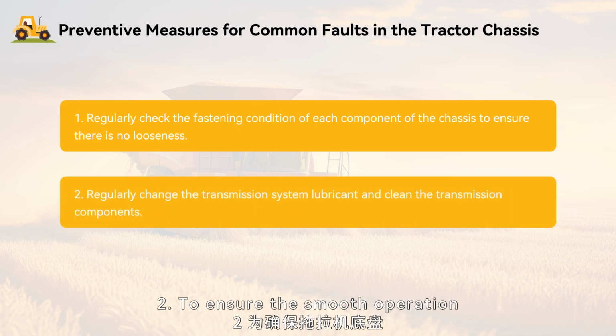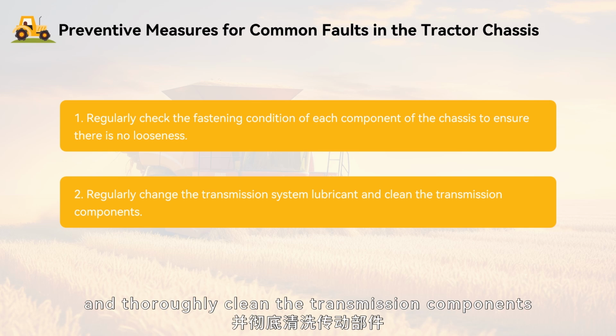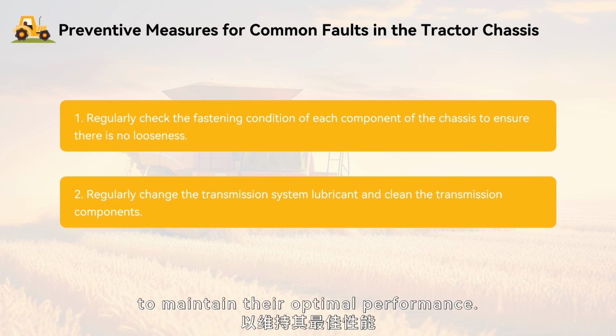2. To ensure the smooth operation of the tractor chassis, it is important to regularly change the transmission system lubricant and thoroughly clean the transmission components to maintain their optimal performance.